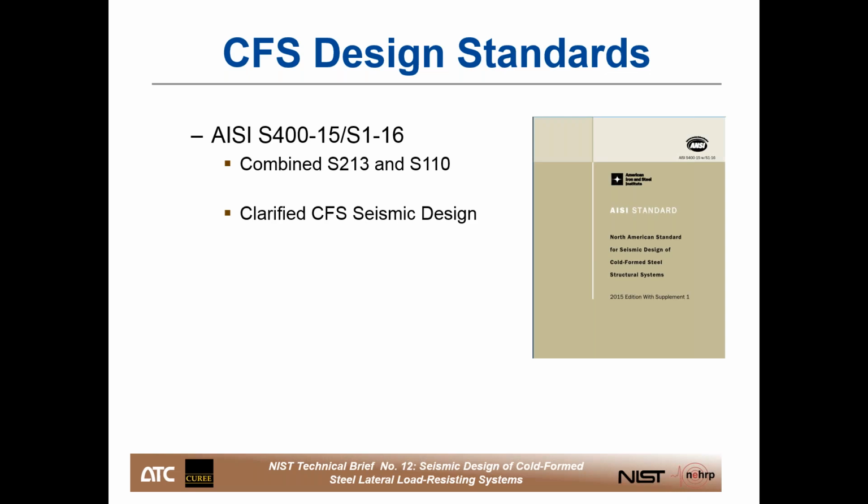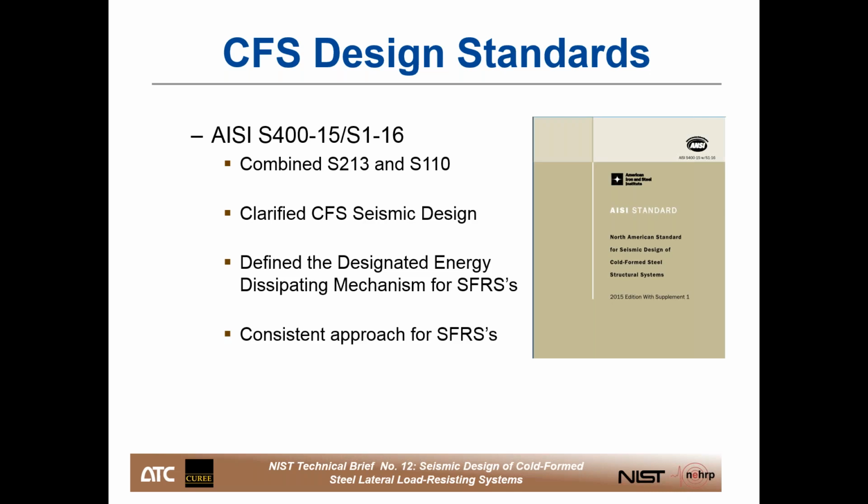One of the goals in developing S400 was to provide clarity and uniformity in the design provisions for CFS seismic systems. Anybody that spent a lot of time digging through S213 might recall that while the provisions were all there, they were sometimes hard to find and not necessarily organized in a way that made it super conducive to understanding exactly what all requirements might be applicable to your particular system. S400 went a long ways towards streamlining that process so that it was just a lot easier to understand what the requirements were and to perform your designs. And that was largely accomplished by specifically defining the designated energy dissipating mechanism for each seismic force resisting system and providing a consistent design approach and language for each of the systems.